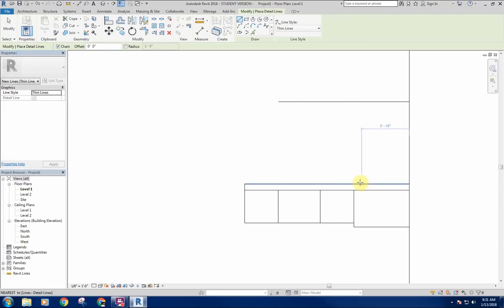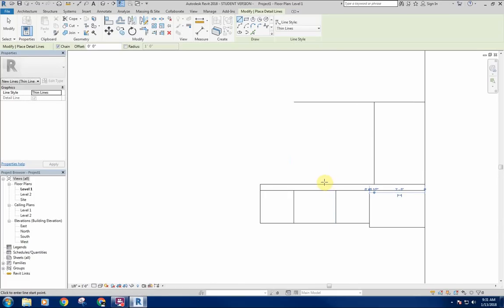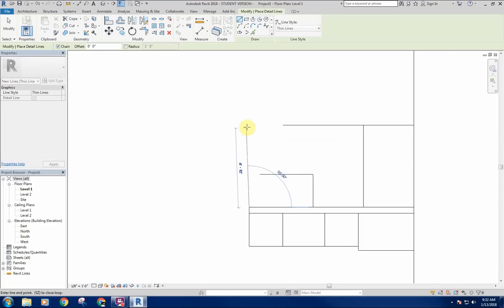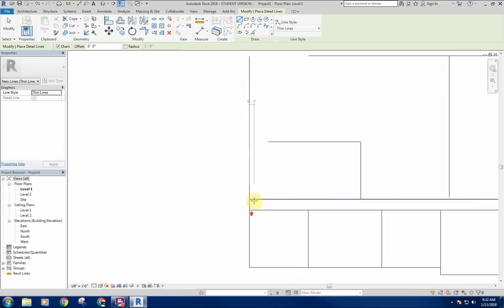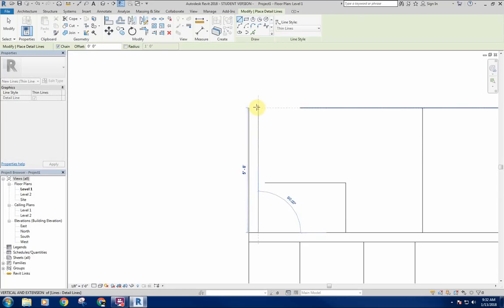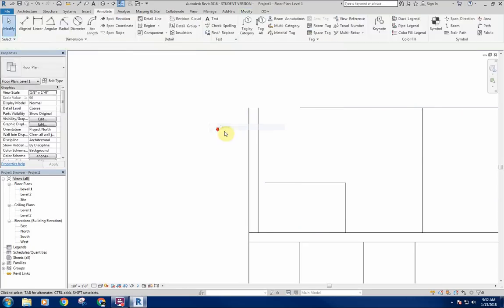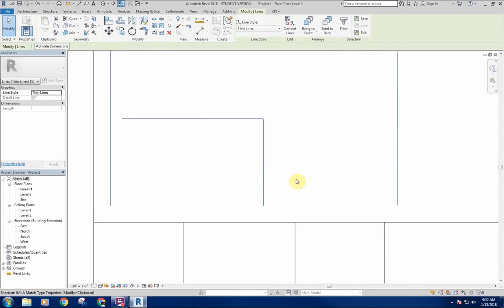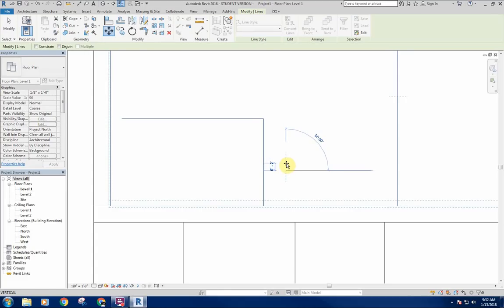So I'll do a 3-foot shower, another 3 feet for my toilet to sit, and then I'll have a 2-foot vanity somewhere in there, and then I'll have my other wall here. So then I get 4.5 inches for my wall. Since this is a plumbing wall, let's go ahead and move this out. We'll get this to be a 2x6 wall, so we'll move this out 2 inches.